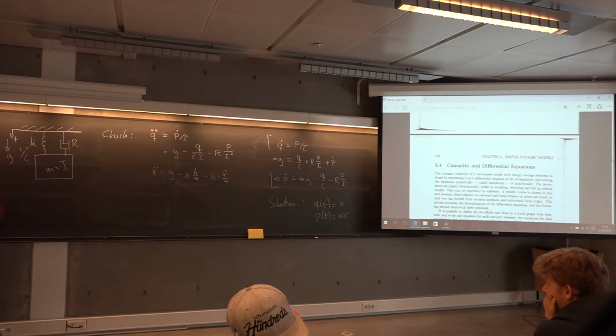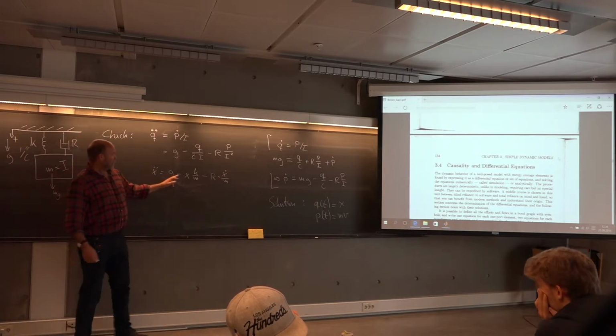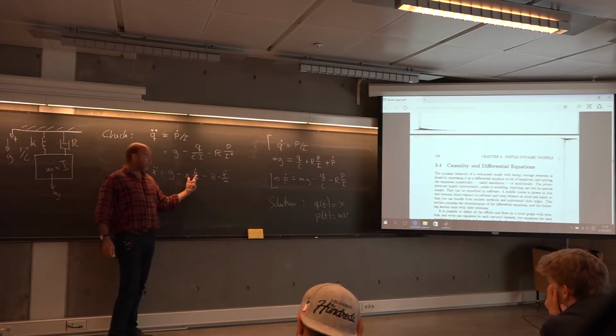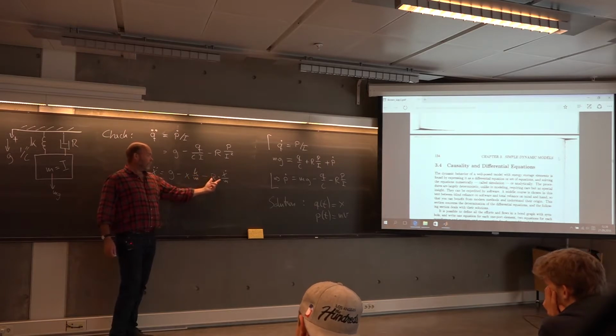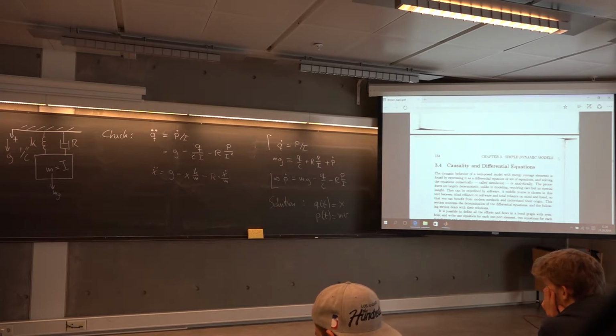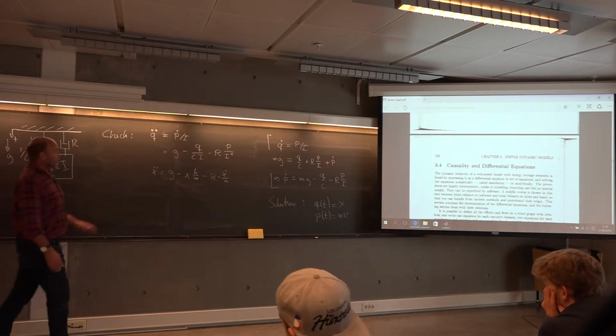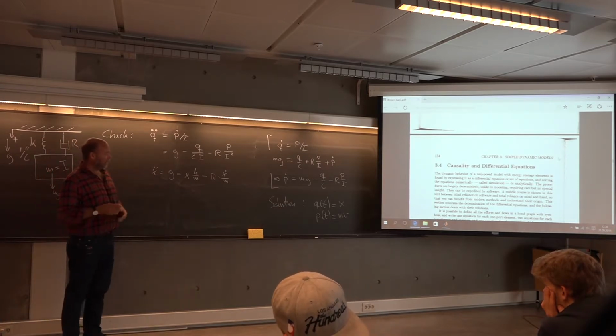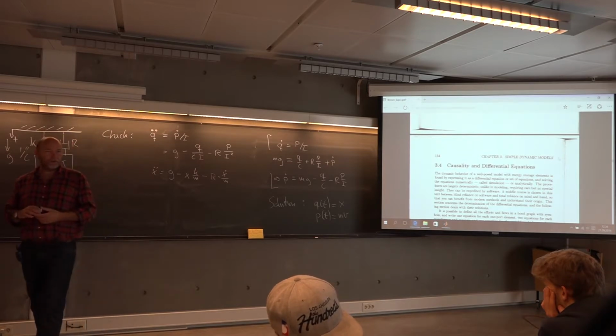And of course, for this simple problem, yes, you could have set that one up directly, couldn't you? What's Newton's second law of motion for this one? Well, you have gravity acting straight down, mg, in the positive direction. Then you have minus the spring force, minus the damping force. So just as a check, yes, it makes sense. Everybody with me on this one?